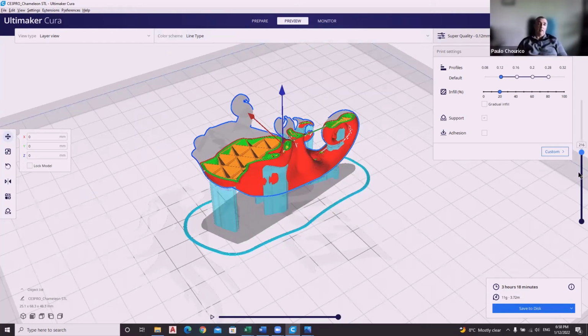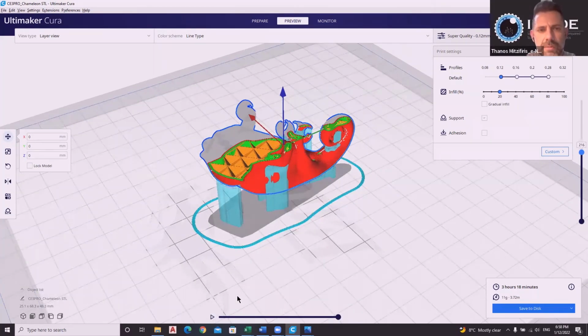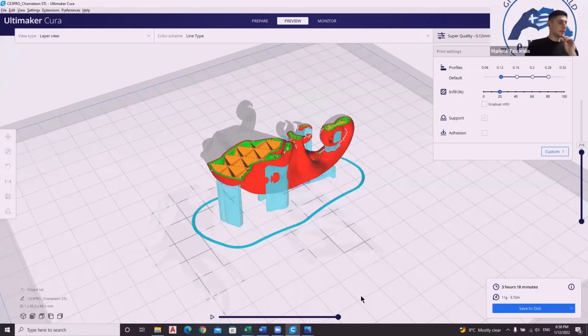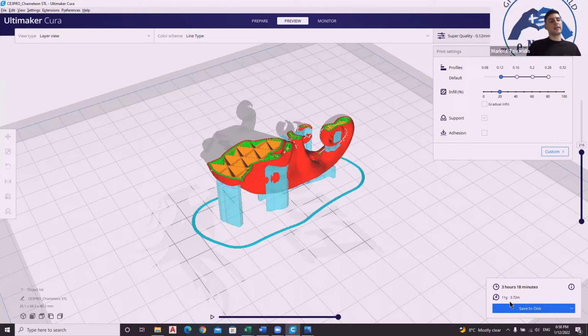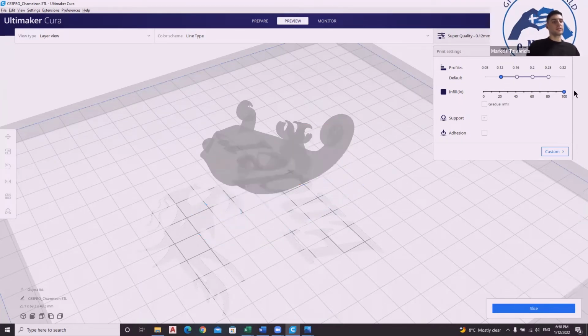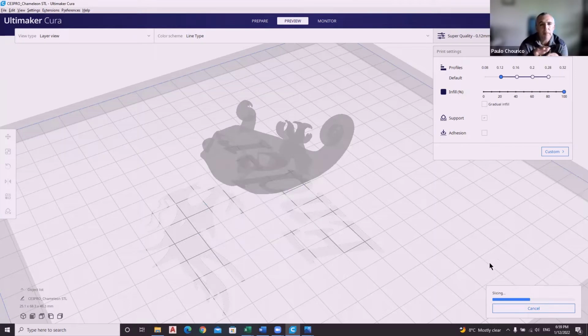But the difference would be very small, as Marcos said. So the difference is big on the infill. As you saw, it's either 11 or 12 grams. When you change that, if I change the infill from 20% to 100% and slice it again, the difference is large.